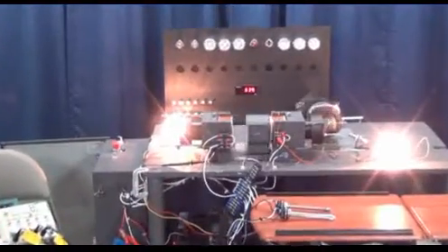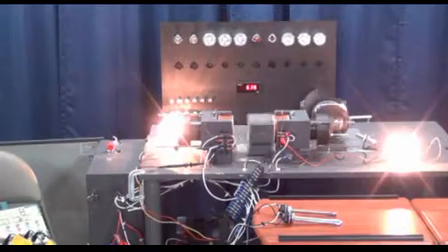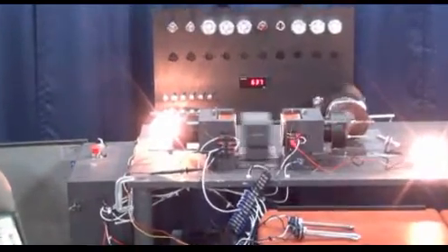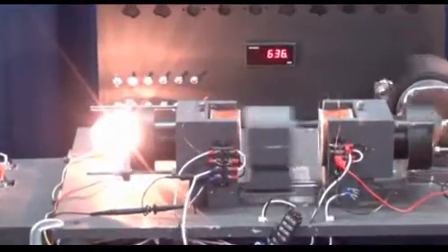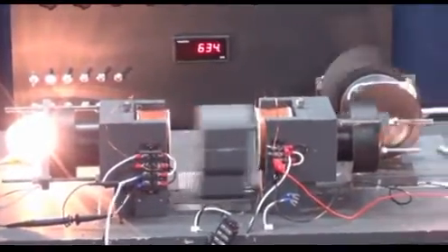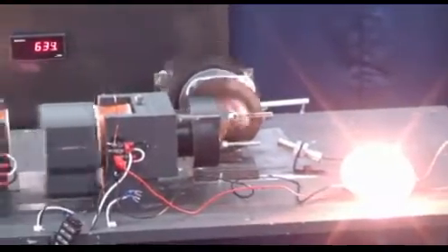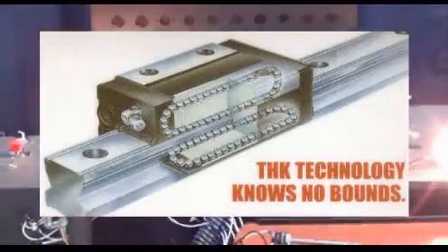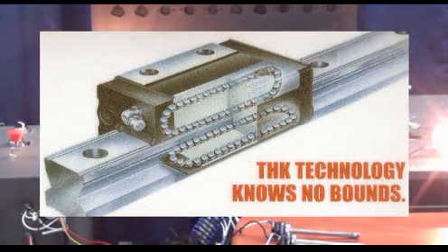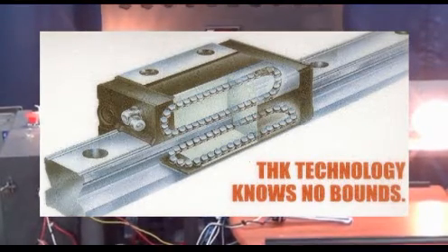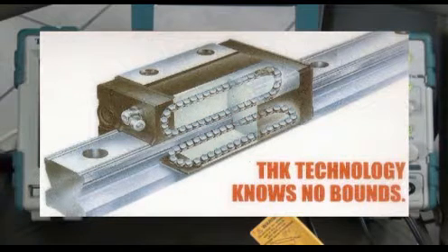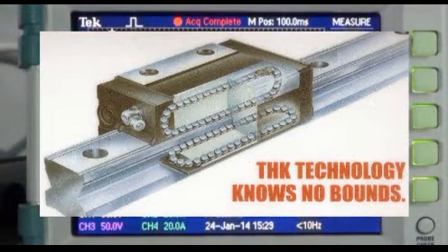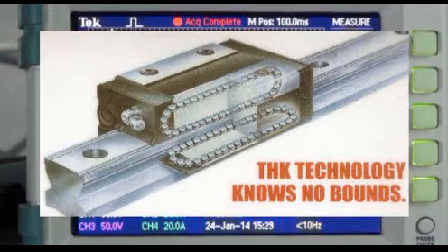After playing around with this device, I've discovered some flaws in my design. Things, if corrected, I'm sure would greatly increase its performance. First, we have friction in the bearings. Here you see a cutaway photo of the type of bearing used on this device. Note the small roller bearings, both the bearing and the slide which they glide on. The magnets on the piston cause these rollers and the slide to become magnetized, which creates friction, and quite a bit.